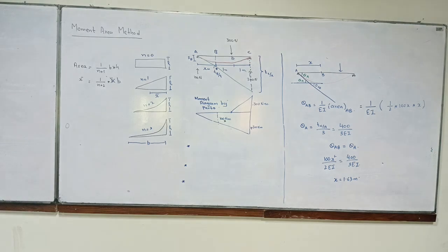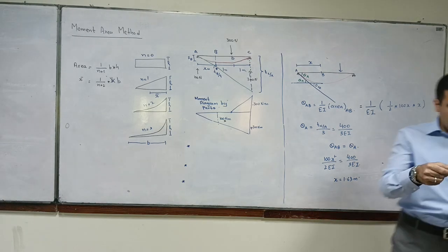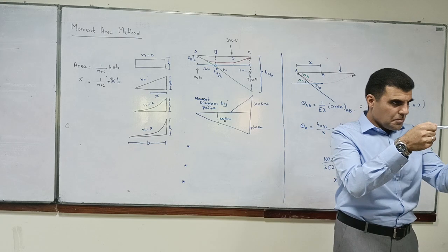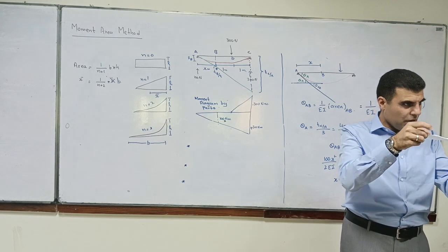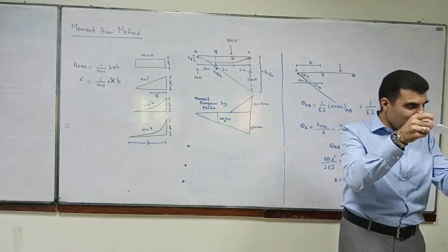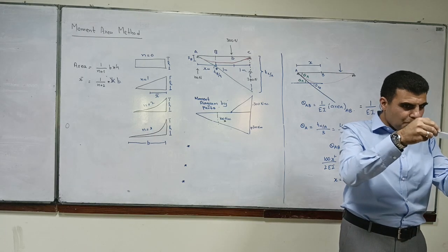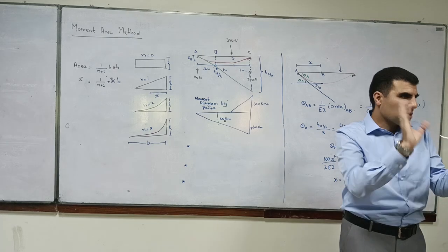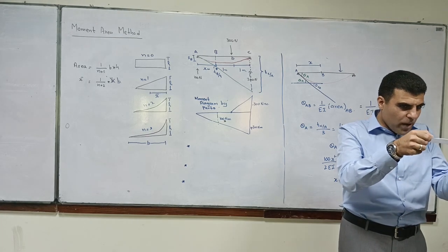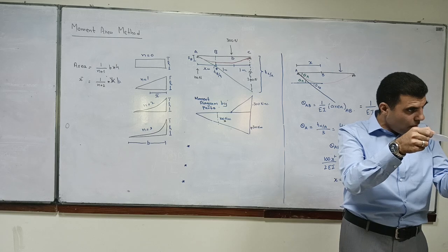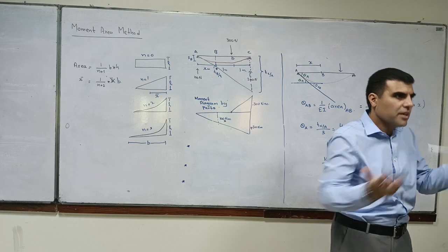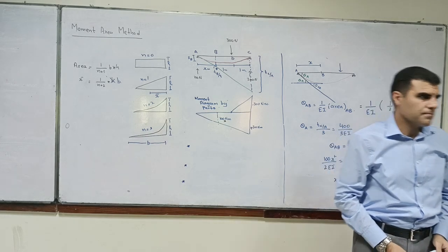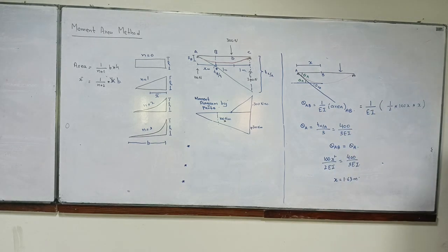Like for example, I've got a beam. Okay, I apply load over here very close to this point. So what will happen? I will get a deformed profile. Imagine that load is very close to my right hand. Still I would get a deformed profile. So that doesn't mean that you will have maximum deflection over here. Maximum deflection can be somewhere in the middle. Unless and until your load is applied at mid-span, you can have maximum deflection.